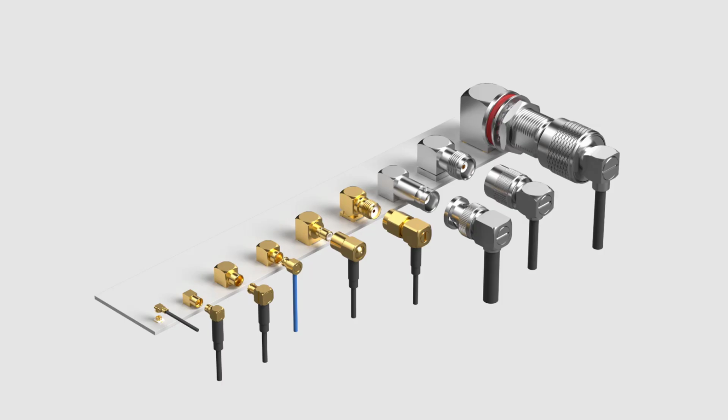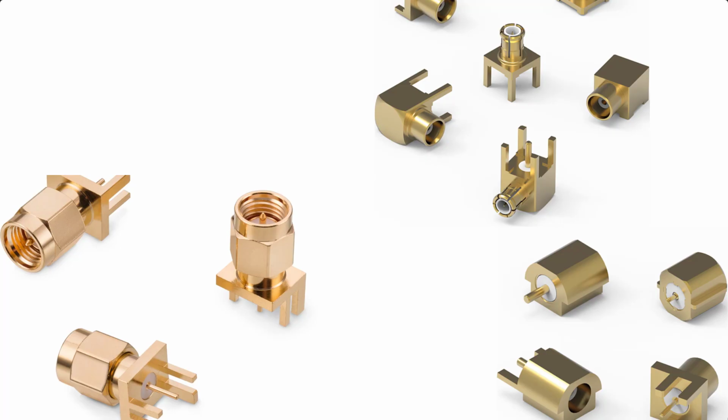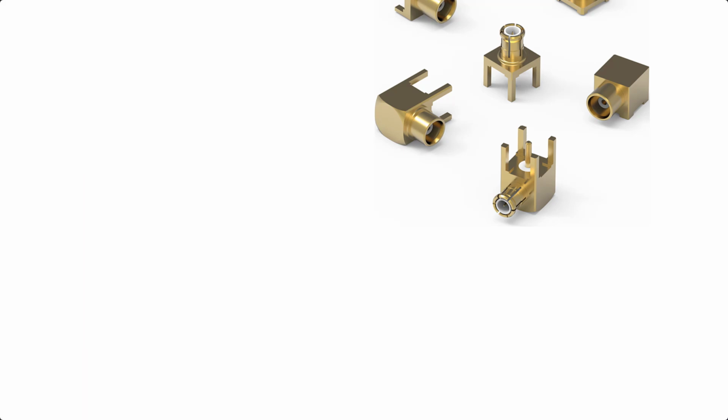Now, for some teams, the real win here is not that the cable exists. The win is that the cable performance becomes predictable and the integration risk becomes smaller. So to wrap it all up, RF systems rarely fail dramatically. They're going to fail incrementally, a fraction of a decibel at a time, a small impedance discontinuity at the PCB-to-connector transition, or maybe a cable attenuation that eats margin at frequency. It could be a bend radius violation that creates a local impedance change, mechanical stress that degrades stability over time, or even production variation that turns a good prototype into inconsistent units.